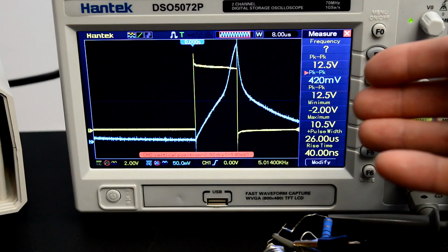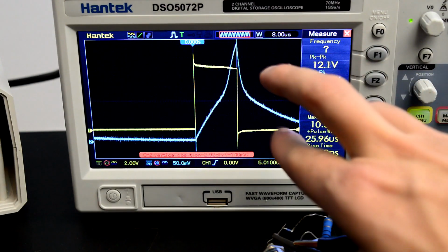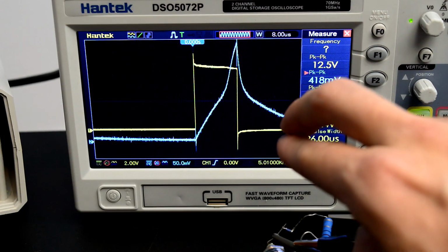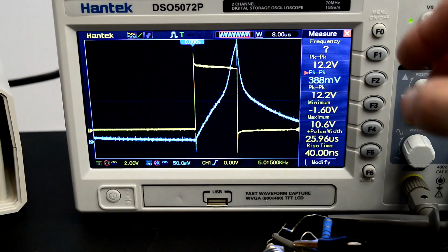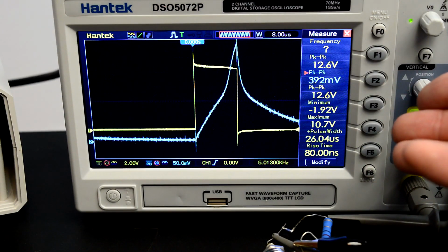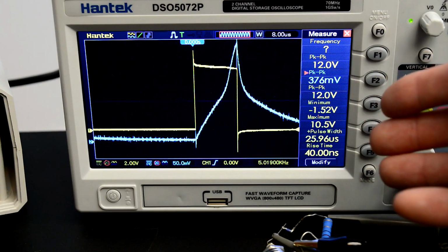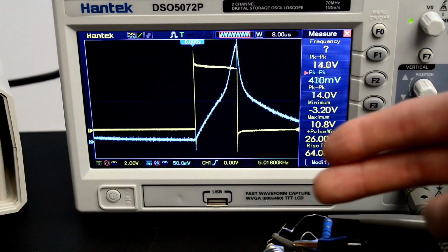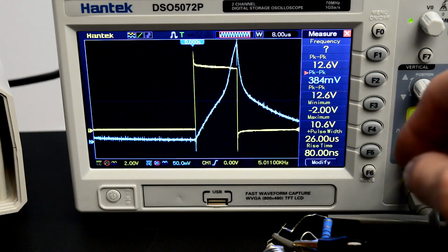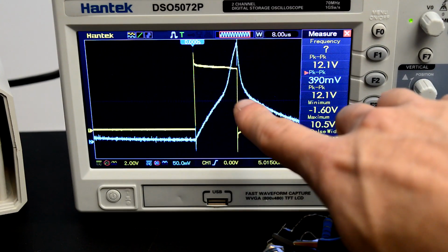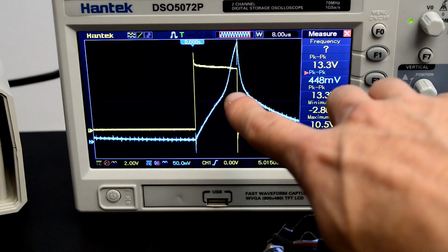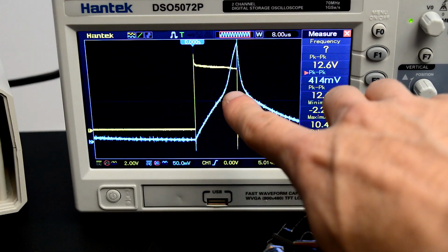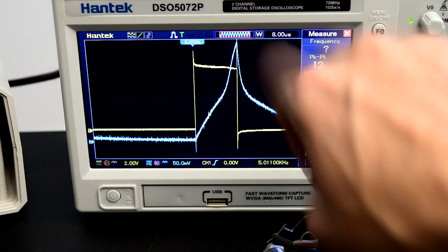So now what I did is I'm applying the same signal amplitude, it's just that it's shifted. So it's no longer a plus minus 4 volt signal applied, but rather it's a plus 8 minus 0 volt signal. And we can see that the current going through the inductor has a different shape. So it starts off going straight, just like before, then it hits this bump, and then it shoots up.